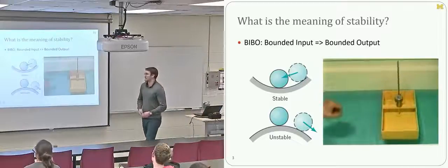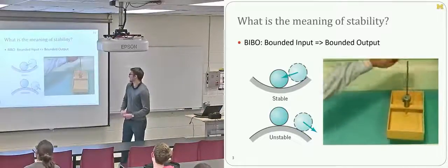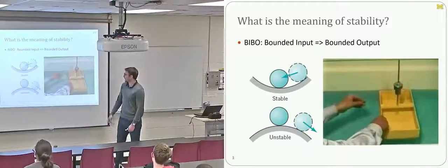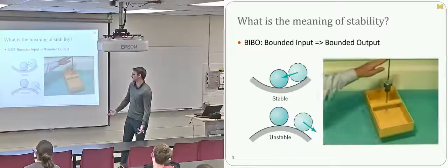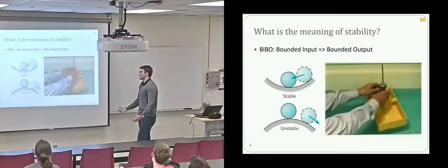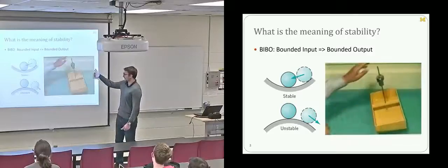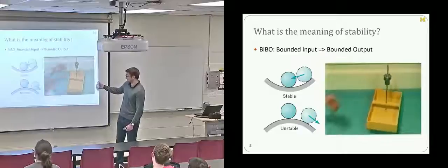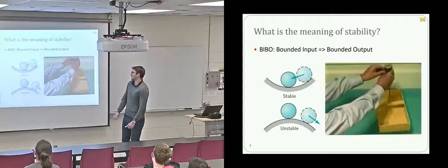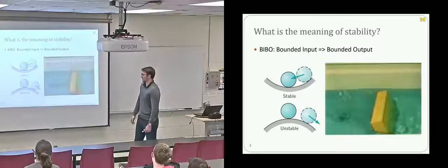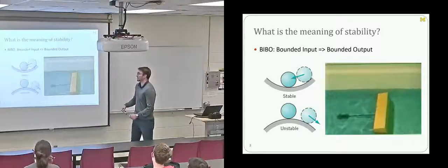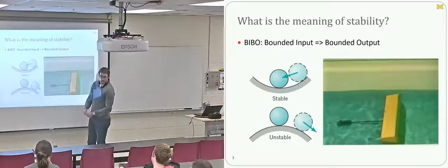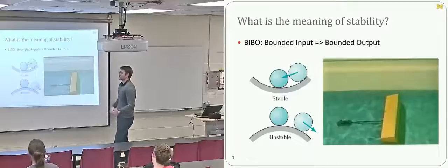And you've probably seen similar demonstrations in early naval art classes, but here's an example of a barge where the center of gravity is fairly low, and as a result, it behaves as any good barge should and doesn't flip over. But as the center of gravity goes higher and higher, it starts to have a more tenuous stability state, and finally, as the center of gravity is raised too high, it just turtles, and you're the naval architect looking for a job. So the definition of stability is, for now, there are tons of definitions of stability. There are as many as there are people talking about stability.